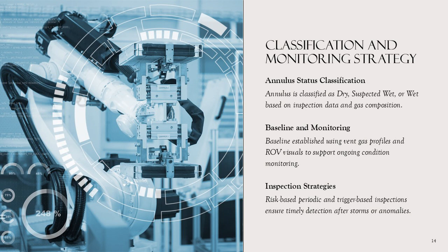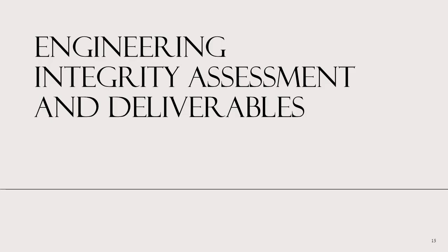and implementing risk-based periodic ROV inspections. Trigger-based inspections occur after storms or abnormal operations. This structured approach ensures timely detection of changes in annulus condition and supports proactive integrity management. Analytical steps and inputs, deliverables and acceptance criteria.